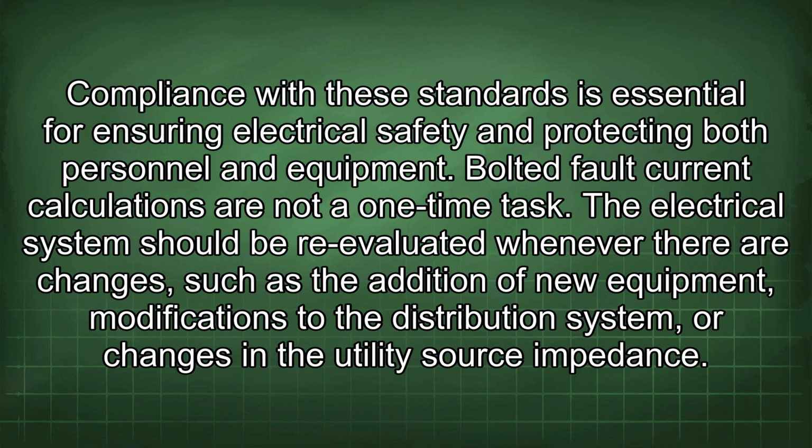Compliance with these standards is essential for ensuring electrical safety and protecting both personnel and equipment. Bolted fault current calculations are not a one-time task. The electrical system should be re-evaluated whenever there are changes, such as the addition of new equipment, modifications to the distribution system, or changes in the utility source impedance.